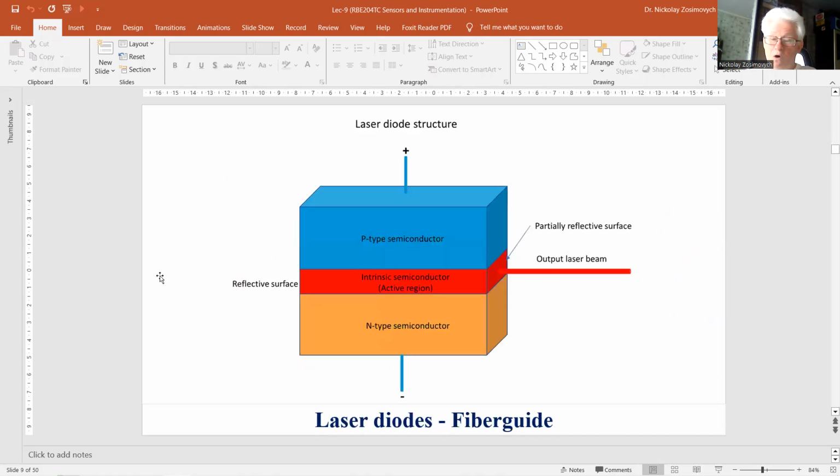Semiconductor laser, or laser diode. It is a low power type having appearance and dimensions similar to LEDs, but whose physical operation is different. Well known from CD and DVD players, laser pointers, and laser printers. Main characteristics are next: material, usually the same, gallium arsenide and other III-V compounds.